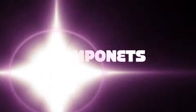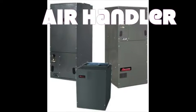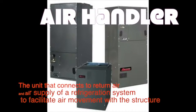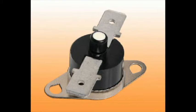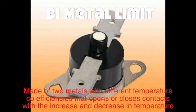Components. Terms. Check. The air handler: a unit that connects the return air and air supply of a refrigeration system to facilitate air movement within the structure. That's an air handler. Bimetal limit: made of two metals with different temperature coefficients that open or close contact with an increase or decrease in the temperature. That's a bimetal limit.